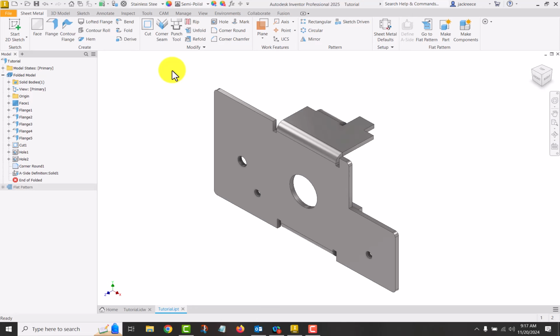This week you'll be doing bend radius calculations. And anytime that you bend metal, it causes it to lengthen or creep, if you will. So you have to take into account the amount that that metal is going to stretch. That's why we do the bend radius calculations so that our finished product is the correct size.